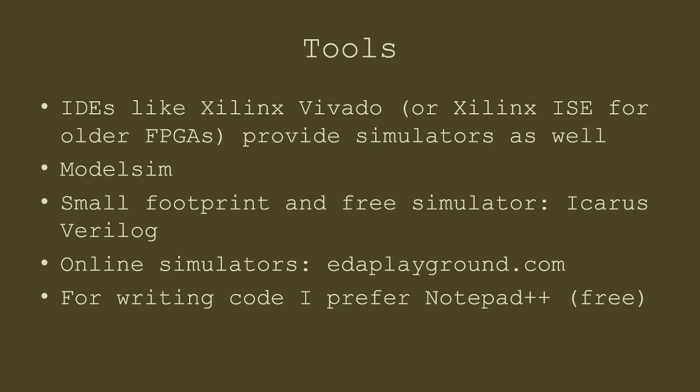So if you want to avoid that, you can use some free small footprint simulators like Icarus Verilog, and some online simulators are also available. If you go to edaplayground.com, then you can simulate using Icarus Verilog as well. For writing code, you can write in any of these IDEs that have an editor as well, but I generally prefer Notepad++.